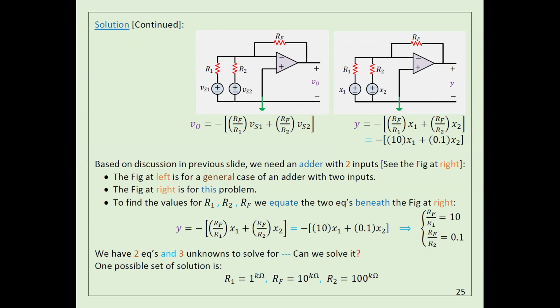But my advice to you, when you assume the values of the resistors, don't make these values very small, and don't make them too big, like open circuits and short circuits. You got what I'm saying? So try to avoid the range of ohms. Also try to avoid the range of mega ohms. Mega ohms is like an open circuit, too much. You understand what I'm saying? Yes, you can select whatever you want here, but you need to be reasonable in the selection of these resistors.